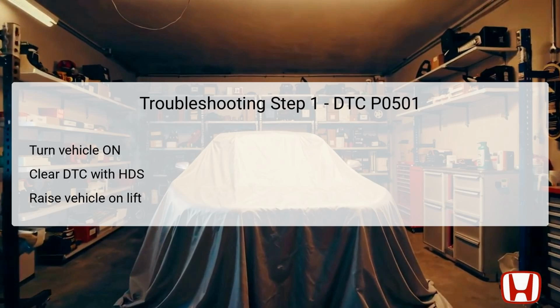After this, the technician needs to enter the Vehicle Stability Assist (VSA) maintenance mode, which alters the performance parameters of the vehicle for testing. Running the engine at 1000 RPMs with the shift lever in D position enables careful observation of the sensor's performance post-DTC clearance.